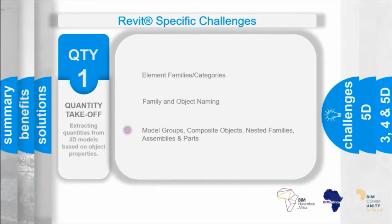And if model groups are used extensively and we need to quantify based on that, we possibly need to make an export of that Revit model that can then be ungrouped and have the estimate based on the ungrouped model that sort of sits on the side. The detractor from that is that we're no longer working in a live collaborative environment. And again, it goes back to that sort of information take process that quantity surveyors are used to, as opposed to developing the model for the whole team.